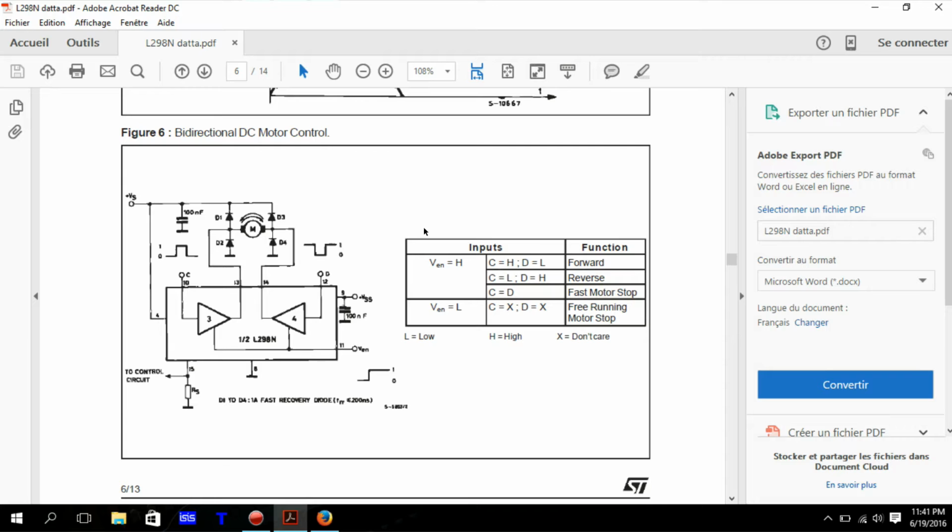You better have Schottky diodes, but I used normal diodes because I didn't have Schottky ones. It works fine so far, but you better have Schottky diodes. And since you have 2 motors, for every motor you need to set 4 diodes.